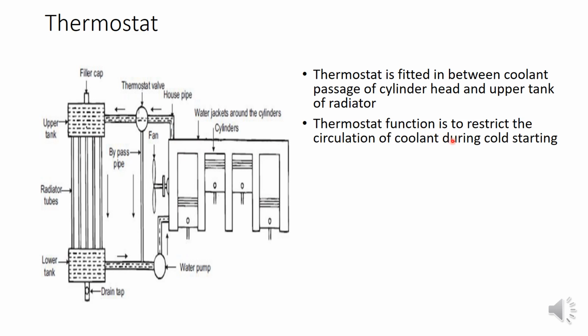And its main function is in cold starting. So what do you mean by cold starting? Cold starting means we have not used an engine for a long period of time and we are starting the engine, we will face some difficulty, and that is known as cold starting, because cold air will be trapped inside the engine. So it will be difficult to start the engine. In that case, this thermostat, a small valve, should be in the closed position so that it restricts the circulation of coolant.